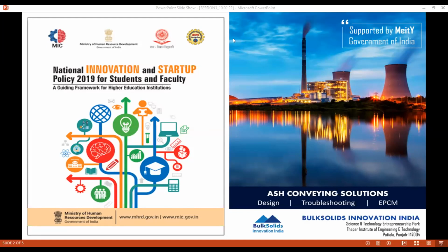When there is an annual or half-yearly plant shutdown, we place the isolation valves below the blow tanks or in other areas required, and open the isolation valve, let the system run properly, then one by one we can isolate the blow tank or other system, do modification and join with the system. With this, the system will not be hampered and the flow capacity will be achieved better.